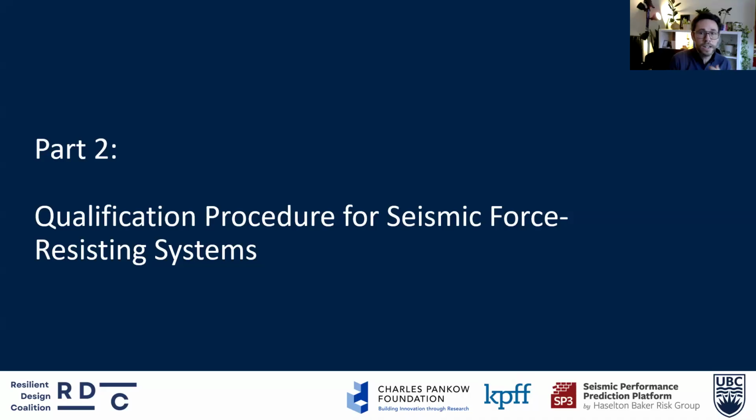In essence, this procedure is intended to be used when developing functional recovery design parameters for new systems that are not yet included in the provisions. So it's a standardized framework for functional recovery, similar to FEMA P695, that some of you may be familiar with, which is used to develop R factors for life safety design.